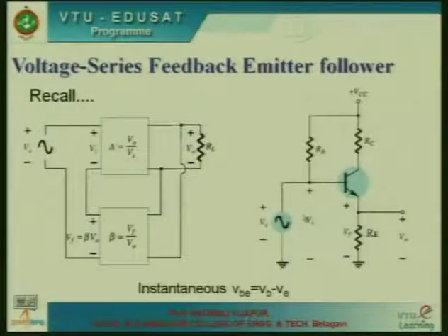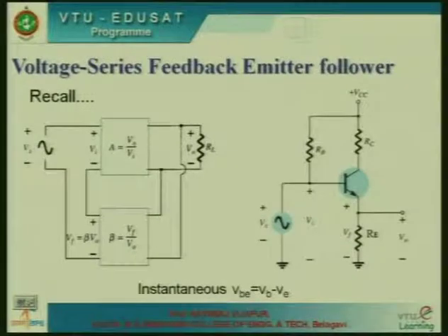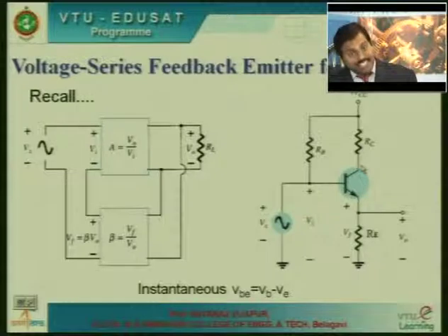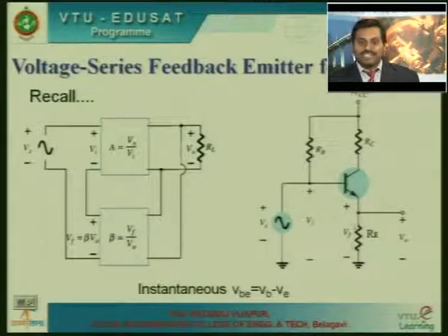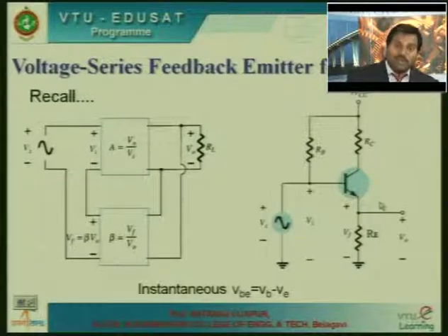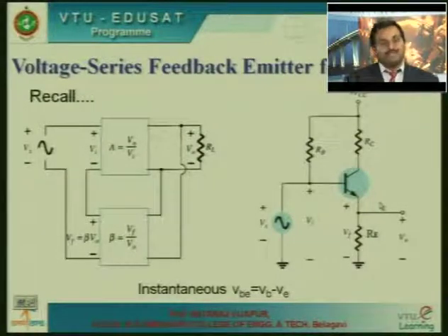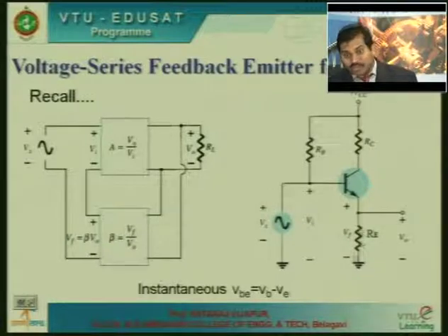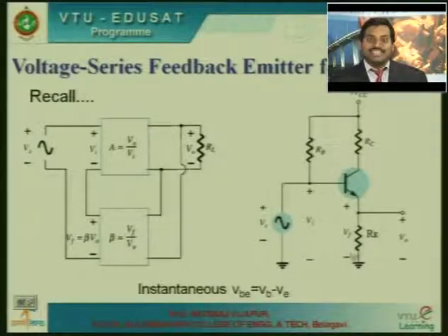You can observe here that when the input AC signal is applied to the transistor, it amplifies the AC signal and the output is obtained. The output voltage appears as Vf across Re. If, due to variations in the load or temperature, some external parameters, the collector current increases, then the emitter current increases. So, the feedback voltage Vf also increases.